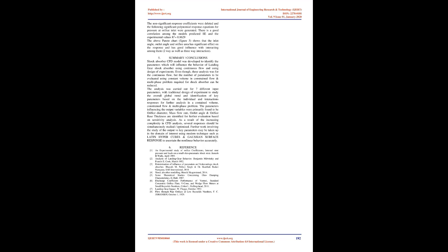The parameters influencing the output variables were primarily found to be orifice diameter, mass flow rate, outlet angle and orifice base thickness, which are identified for further evaluation based on sensitivity analysis. As a result of the increasing complexity in CFD analysis, several responses should be simultaneously studied and optimized. Further work involving the study of the output versus key parameters may be taken up in the domain of interest using modern techniques such as Latin hypercubes and Gaussian surface response to ascertain the nonlinear behavior accurately.